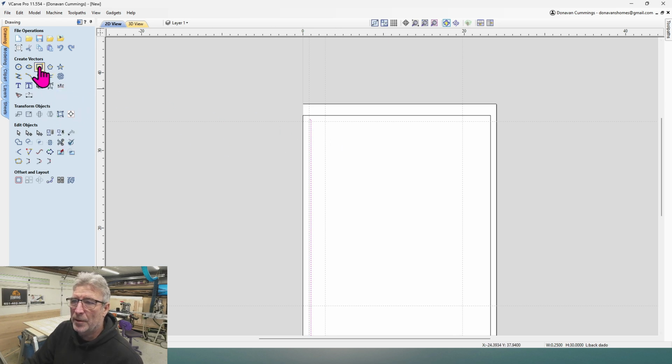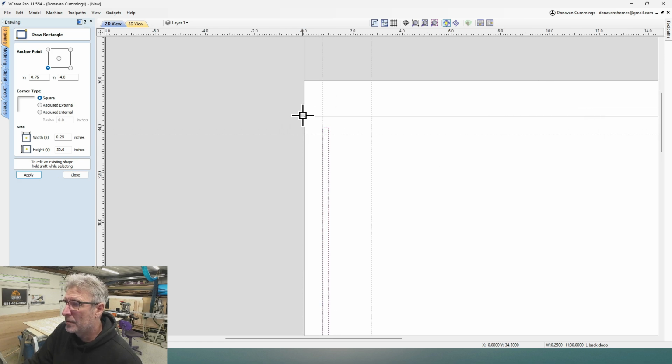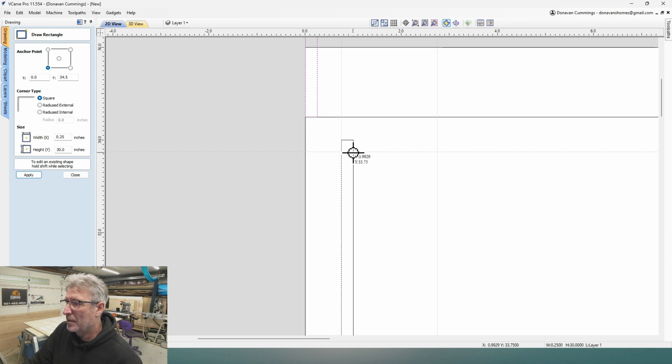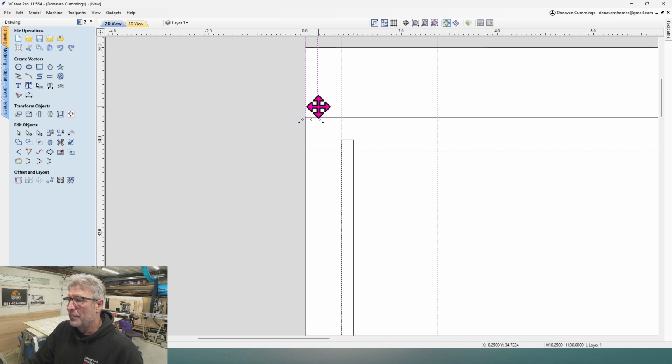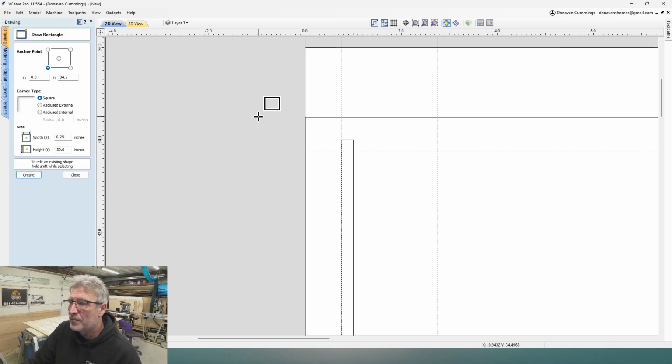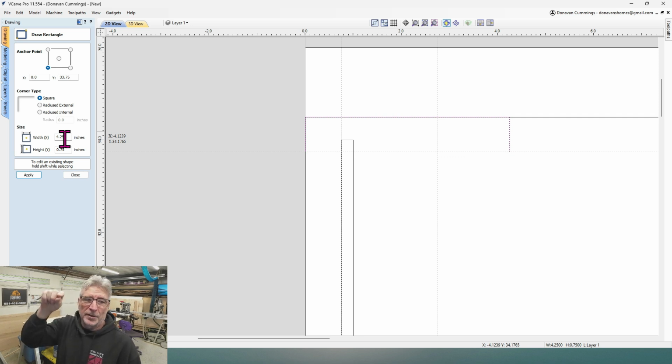So I am going to go up again, hit up in here, zoom up. And it created a box I didn't want. So I want this to be 3/4, and I'm going to go to 4 1/4. Now this one I can actually see it, so I can just drag and drop in there. So I can apply that. Now, again, 3/4 of an inch by 4 1/4 inches is going to be my dado cut for this. We're going to make our stretchers actually at 4 inches, and then that'll help a lot, so we don't have to worry about putting fillets or something on there.